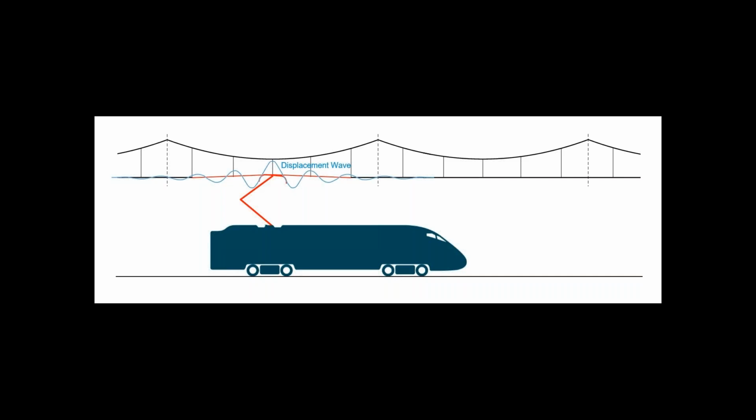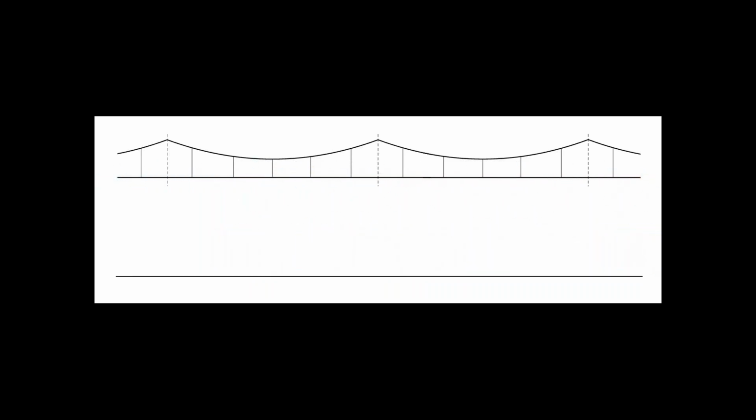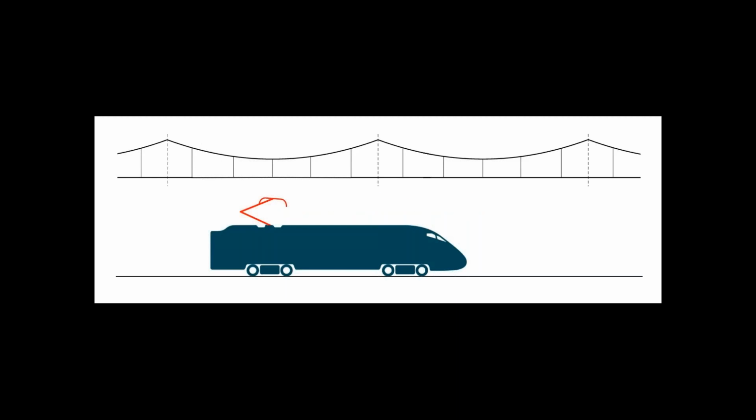And because of that, our UK standards require that the mean contact force plus or minus 3 standard deviations should always be between 0 and a value that's speed dependent, but it's roughly 300 newtons. So if you keep that 0 to 300 as being the sweet spot in your mind, you'll see what that looked like at Steventon later on.